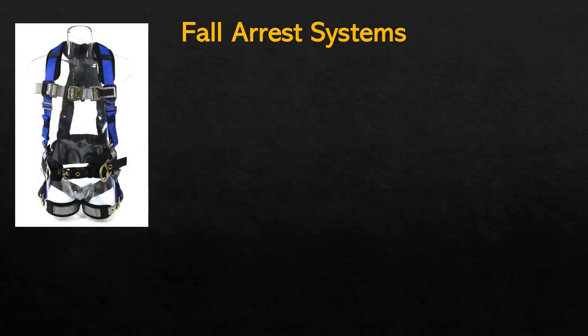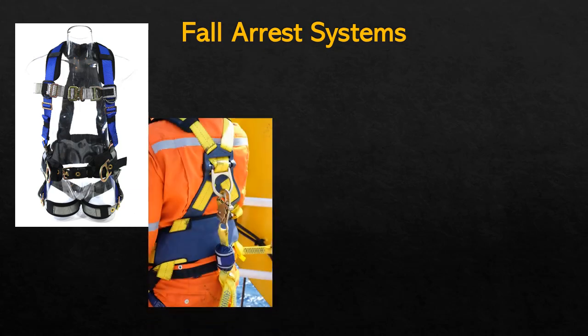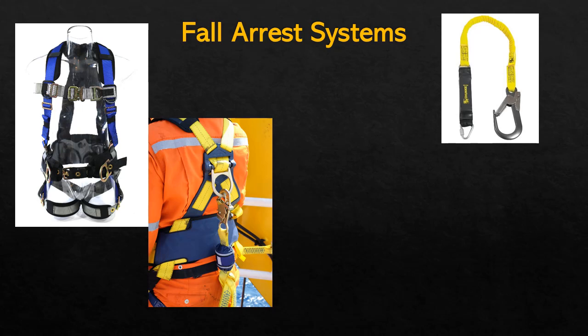This is kind of what you would see when you have a proper shock-absorbing body harness as part of a personal fall arrest system. It'll have a hook on the back, like you see here, to which the lanyard attaches. The lanyard itself has significant shock-absorbing characteristics, and it'll have the hook on one end and then a smaller carabiner hook on the other end, or sometimes it has dual hooks. But the hooks on a lanyard need to be routinely inspected to make sure that they don't come out of place, because if they do, there's a potential that people could slip out of them.